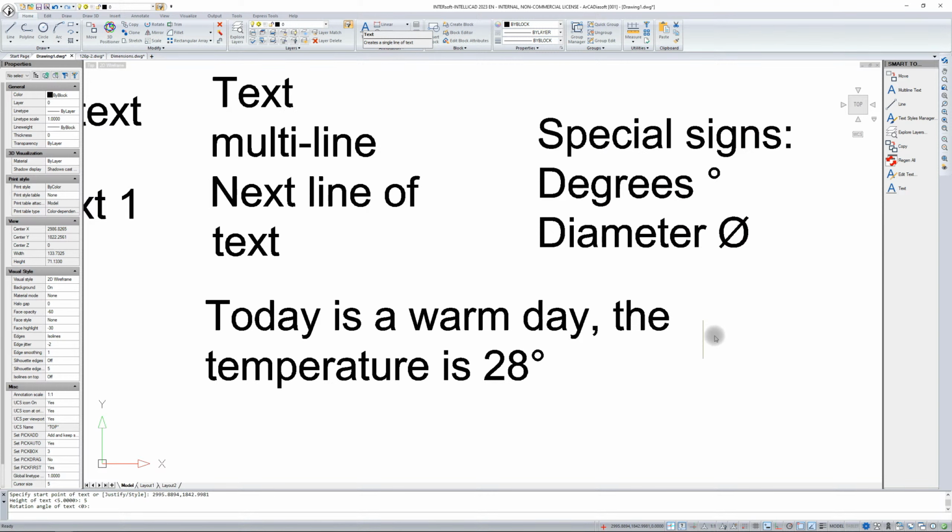Now, let's say that it's going to be the value of 20. Just so that you can see that, I want to enter a 2 in subscript. That's why I put a space here just in case. The special character starts with a backslash, then U with a plus. And here we have 2082 in this font. So you can't use this option. That's when you just need to change the font.